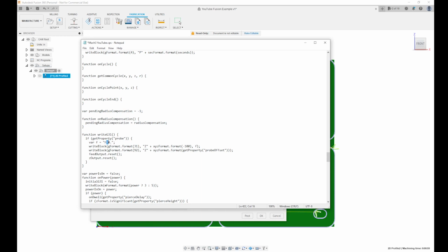You may want to change this to something else if you are using millimeters per minute. I don't know the equivalent value, but it will be different. Ten inches per minute is what it probes at, because it was probing at like 50 inches per minute, which was way too quick. So change that to a slower value than what it defaults to, using the equivalent in millimeters per minute if needed.